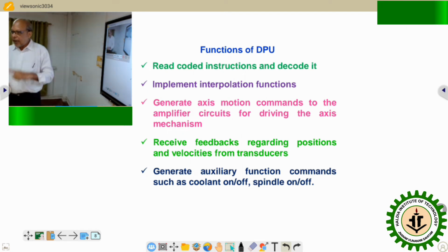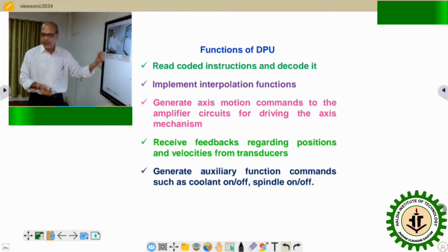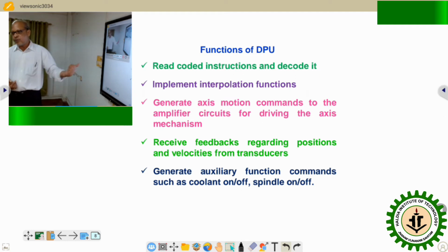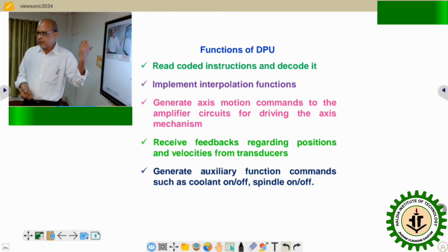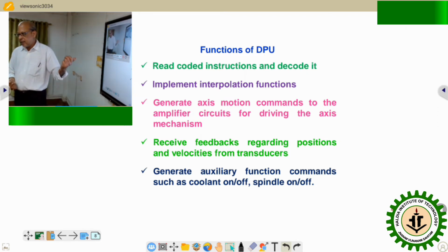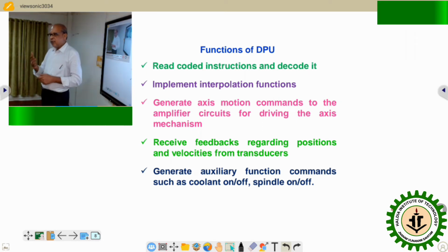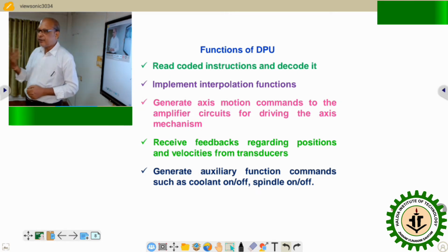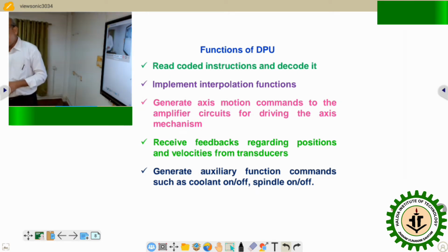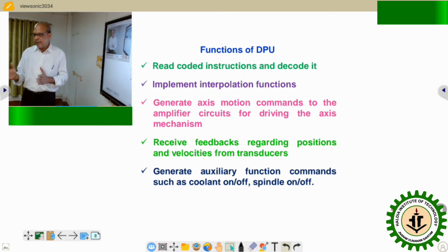Higher level interpolation is also possible, but usually those are not available in any general purpose or commonly used CNC machines. Those are very complicated and require some software. In that case we ought to express or emulate through free form surfaces, which cannot be represented by common analytical functions.